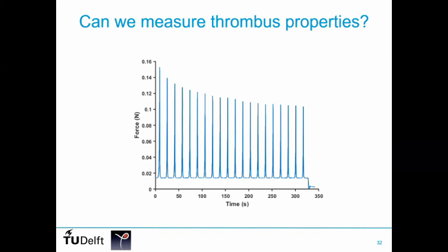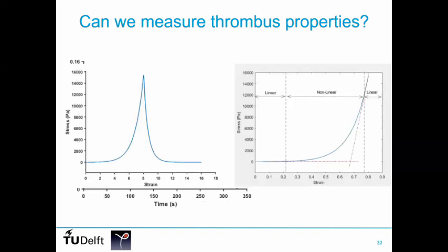And if you zoom in here, you can see some other things, that this seems to be having a lower slope at the beginning of the compression, and there seems to be some asymmetry between the loading and unloading curve, indicating viscoelastic or poroelastic behavior of your specimen.